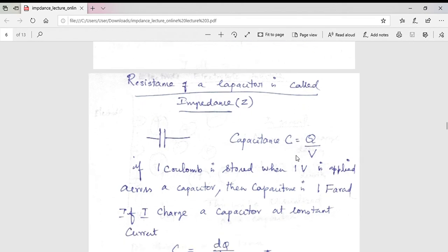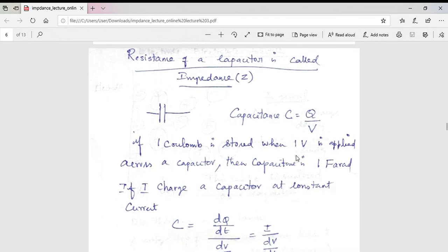So it's very clear from the above example. If someone asks you to define what a resistance is, we can say it is the obstruction offered to the flow of electrons. The copper wire offers the least resistance, so the voltage drop is smaller, whereas a resistor of 100 ohm offers high resistance, so the voltage drop is about 100 volt versus the 3 millivolt that we have seen for the copper wire. So that's very clear.